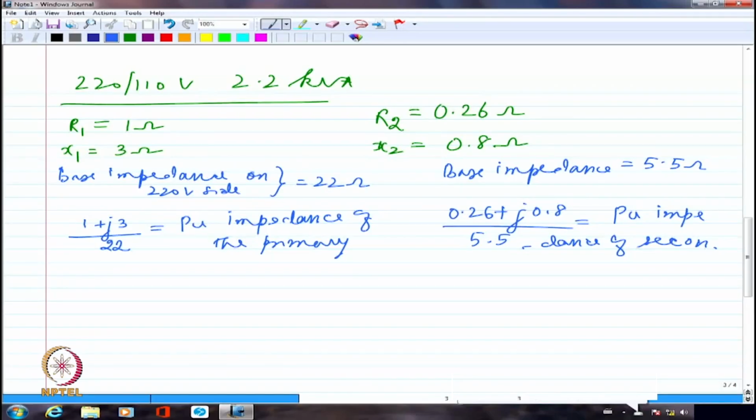If for one of them I get 1 per unit, and for the other one I am getting 22 per unit, for example, I know for sure I have goofed up somewhere. So the per unit values give you a ballpark estimate, so that just by inspecting them, you would be able to say whether you have done all the calculations correctly.